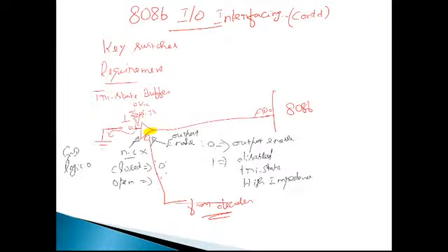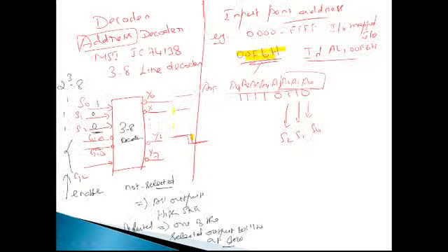So coming back to this particular example, the more appropriate thing is that you connect with Y6 of the 74138. It's as simple as that. But the design is still not complete. What will happen to this G1A bar, G1B bar and G2?